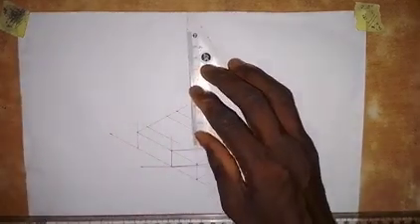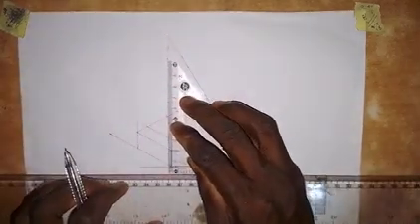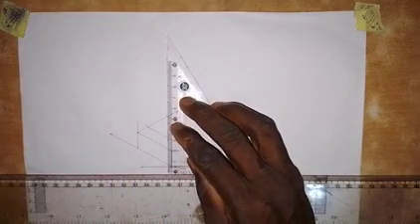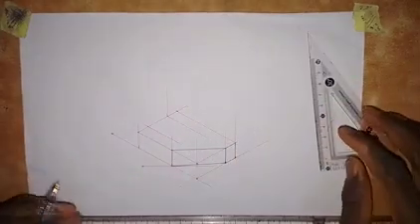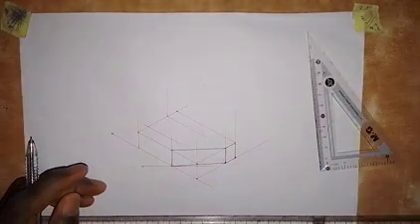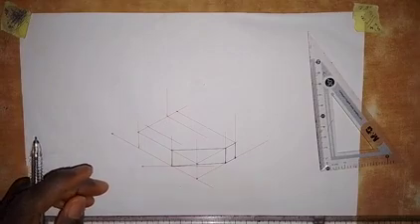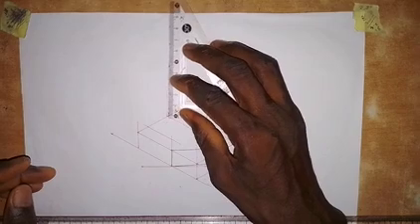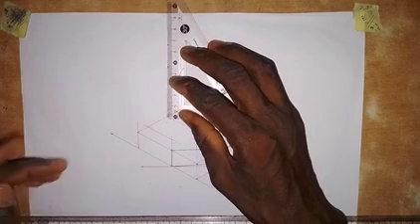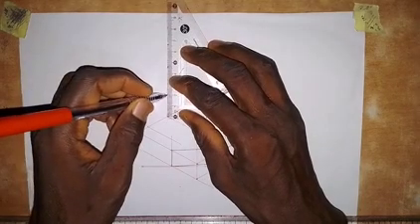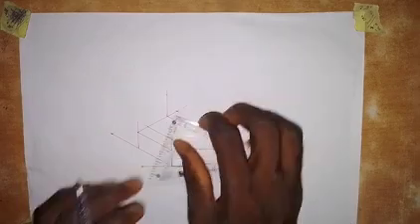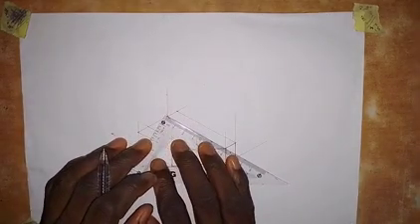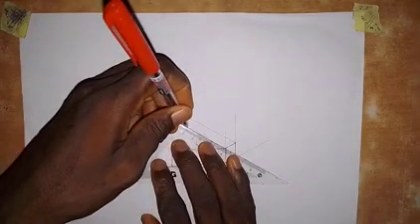Okay, so on this point I will erect the vertical line on this point here. So erect the vertical line on this point. And then so the total height is 35. So the total height is 35 and we have taken 15 out, so the balance is 20. So we take a measurement of 20 millimeters here. So this is 20. So we are going to create a square of length 20. So I will come here and also take 20 to this side.